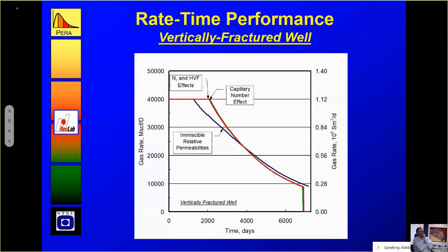And we were trying to match the bottom hole pressure measurement. Okay. Yeah. So we were trying to manipulate, and we knew that there is an excessive fluid leak-off, so one of the possibilities was that this high pressure drawdown can be explained by excessive fracture fluid leak-off or clay swelling.